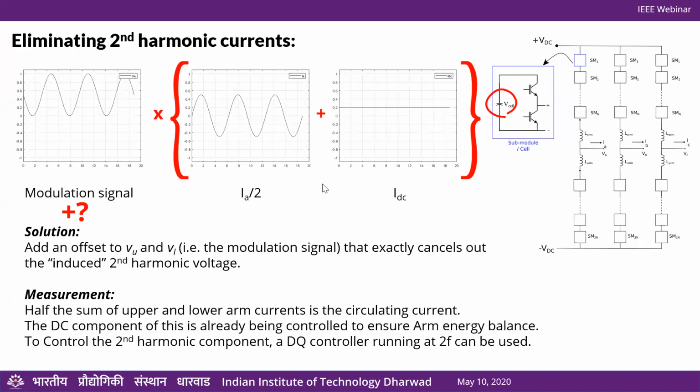is, how do you decide phase shifts or phase angles for, I'm assuming, PSC PWM, phase shifted carrier PWM. So there what we do is, let me be clear here, n modules in the top, n modules in the bottom. So we have 2n total number of modules. We are going to have 2n carriers, right?